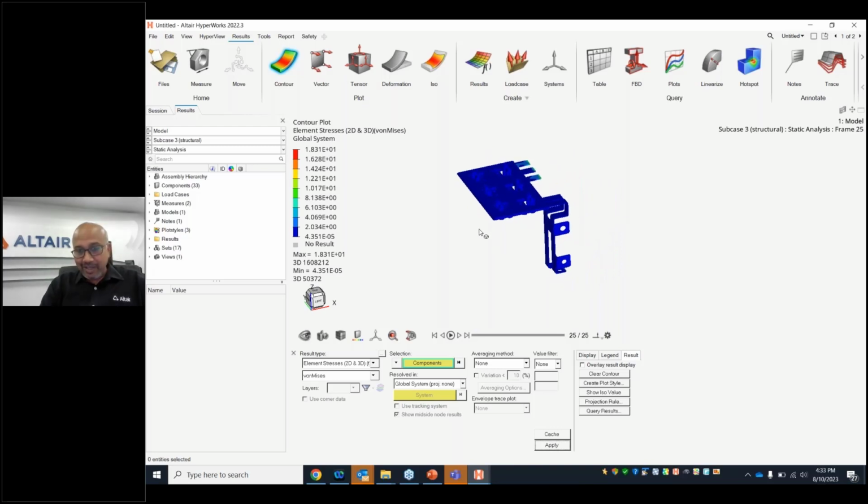In this short time, of course, overshooting by 4 minutes, the attempt was to show the setup for the electrical simulation. Further, what is not shown here is the contact side. It is possible that you perform a nonlinear simulation and establish contacts, and from the contact pressure and the contact clearance, there is a possibility of change in the conductance. So by taking that into account, you can perform the same electrical simulation downstream. Those are also possible in the electrical simulation.